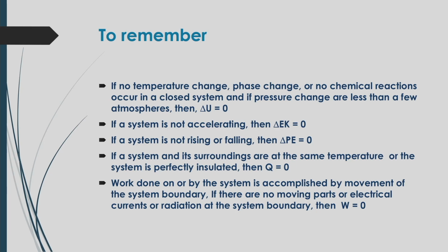In this case you have to remember that if there is no temperature change, no phase change, no chemical reactions in a closed system, and pressure changes are less than a few atmospheres, then the internal energy change will be negligible or almost 0. If a system is not accelerating, the kinetic energy change will be 0, and if a system is not rising or falling, there will be no potential energy change.